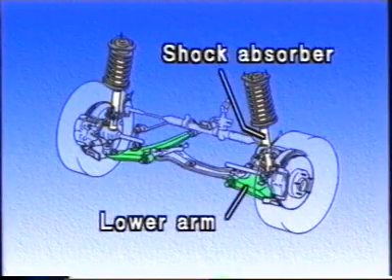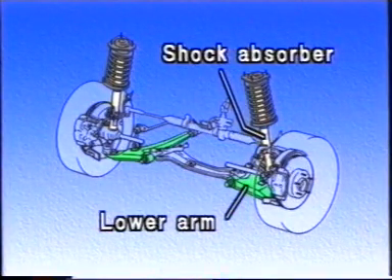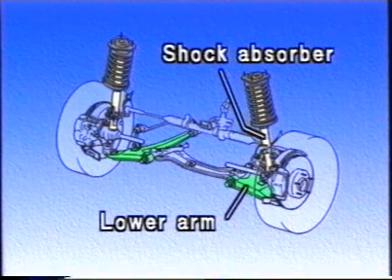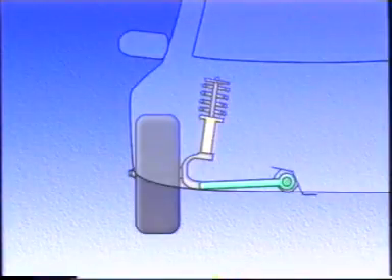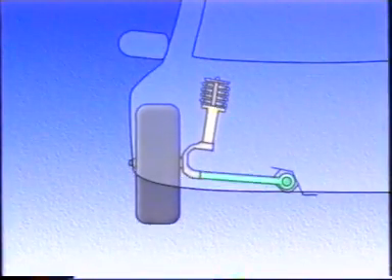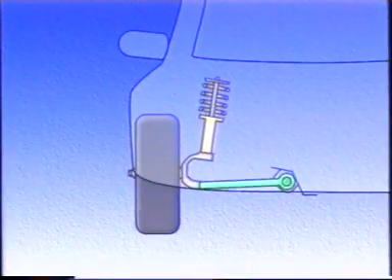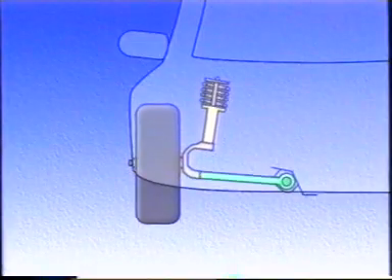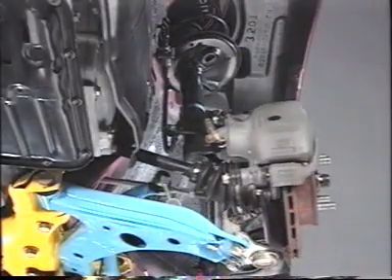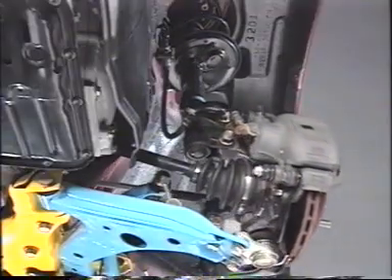The upper end of the strut, incorporating the shock absorber, is mounted onto the body. The lower end and the steering knuckle, forming a unit, are mounted onto the body via the lower arm. The strut functions as part of the linkage and, along with the lower arm, provides longitudinal and lateral support. The strut is also allowed to rotate freely and functions as a kingpin.